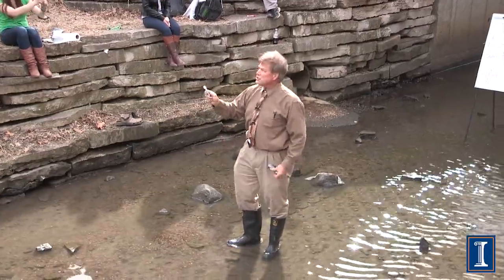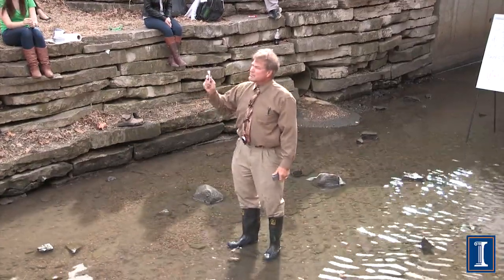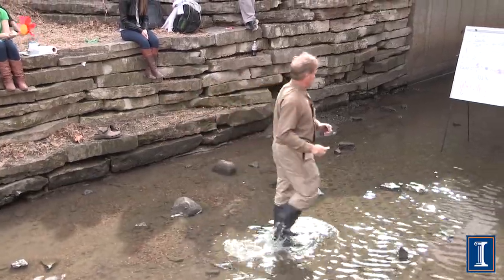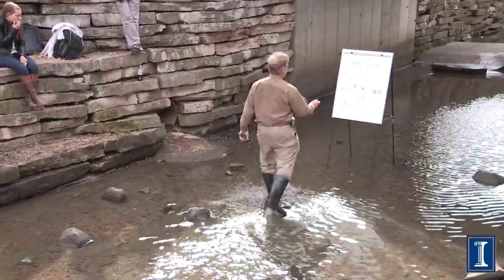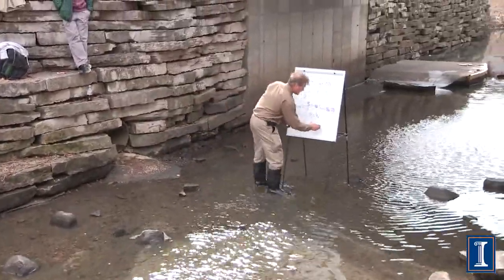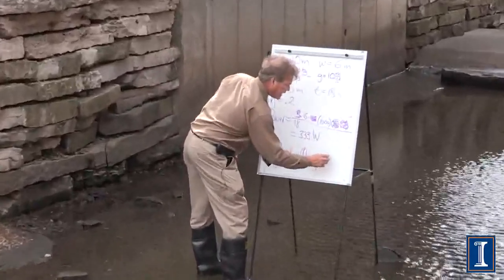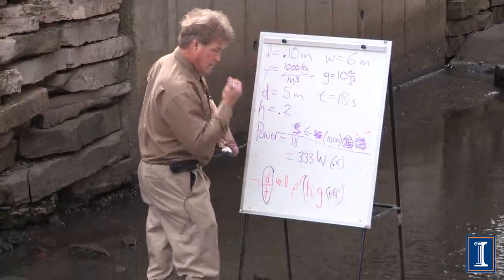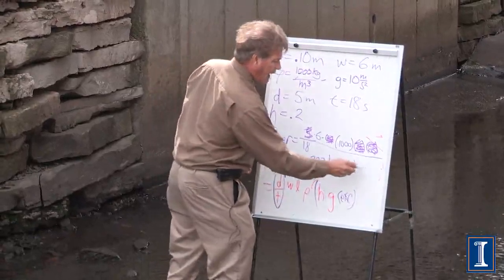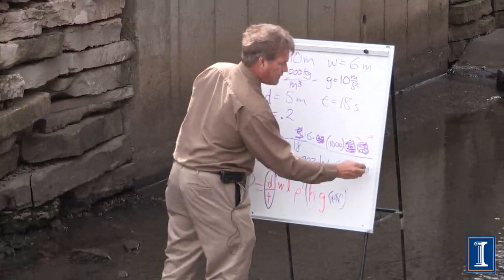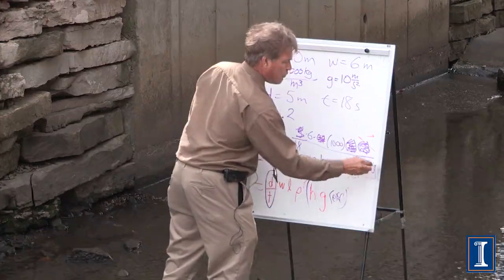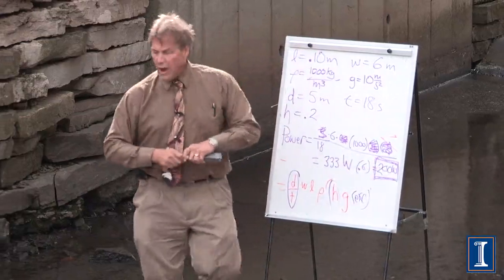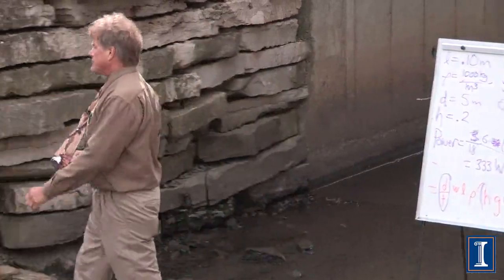And the second is, if you do have one of those turbines, its efficiency is actually around 0.6. So there's one more thing in this equation, which is the efficiency of the turbine. So let's say we can get 6/10. That now is 200 watts. 200 watts. 2 light bulbs. Way short of a hairdryer.